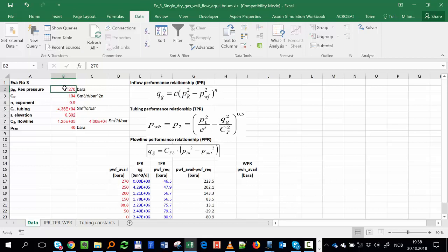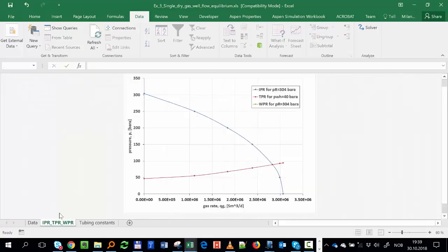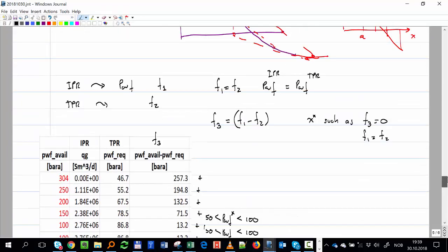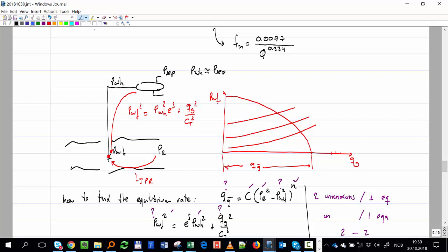Now let's do one thing that I think is going to be a bit confusing, but I think it's a way to learn. In our well, let's move the equilibrium point. The equilibrium point here was at the bottom, and we use that, for example, for design of artificial lift, because we normally put the gas lift valve or the ESP, electric submersible pump, down here.